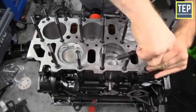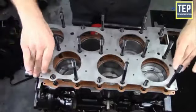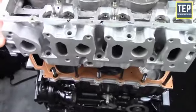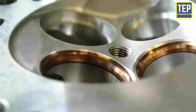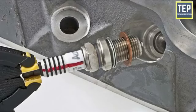The cylinder head is attached to the cylinder block using studs fixed to the block. Gaskets are used to provide a tight leak-proof joint between the head and block. The cylinder head contains a combustion chamber above each cylinder, and it also contains valve guides, valve seats, ports, coolant jackets, and threaded holes for spark plugs. It incorporates passages for the flow of cooling water.